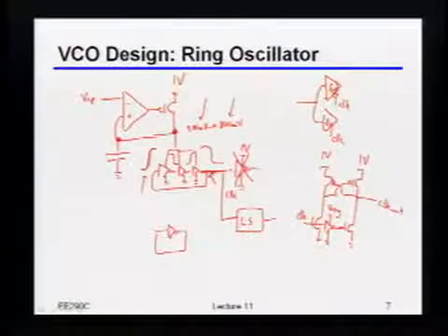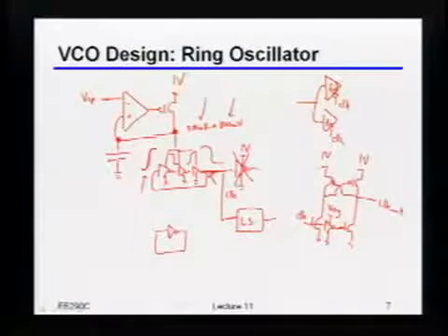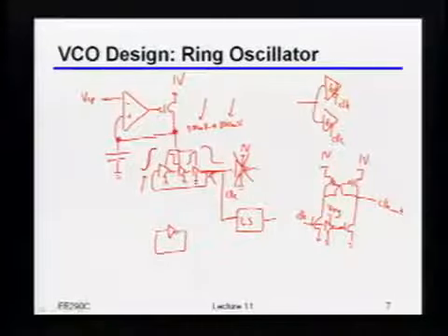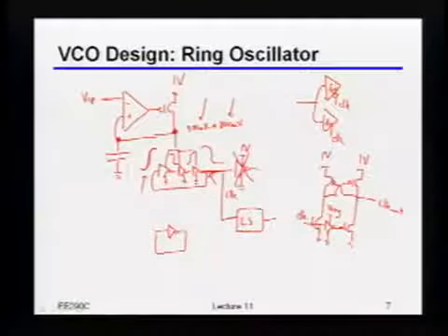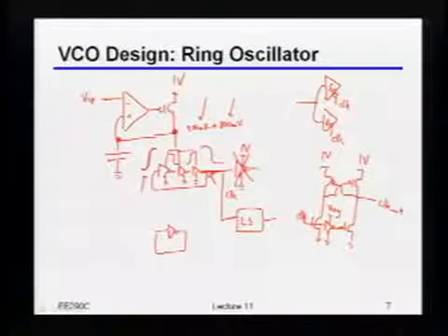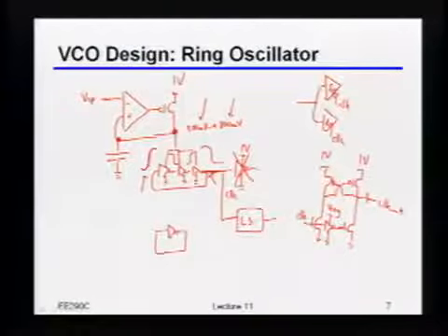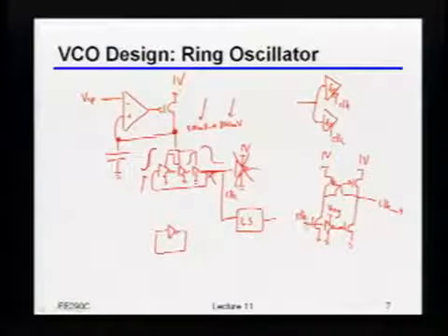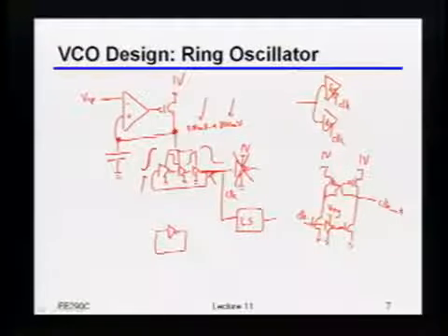Because the drive strength is changed when the regulated voltage is changed for the NMOSes. Okay, I think what you said was correct, but I just wanted to give a more intuitive explanation. Let's even assume that I have a fixed regulated voltage. In order to cause this thing to rise, I basically have to make this go high, which pulls this down, which turns on that PMOS, which finally makes this go high.